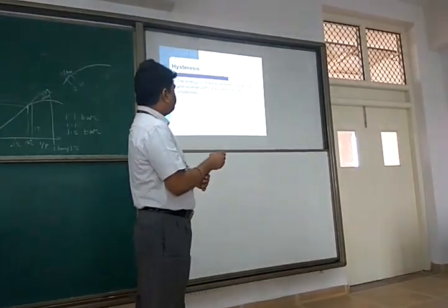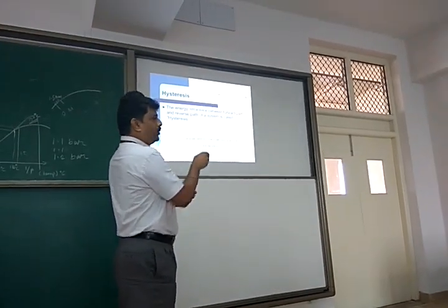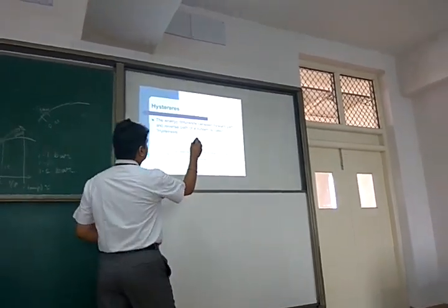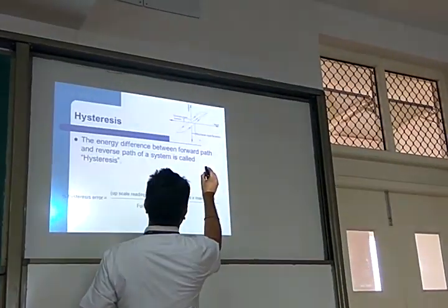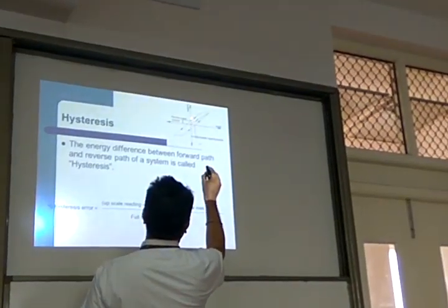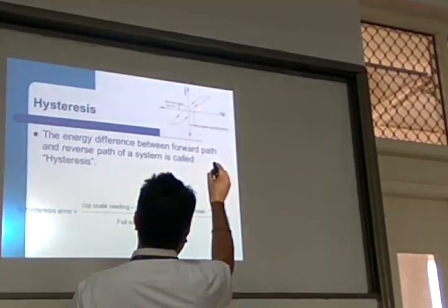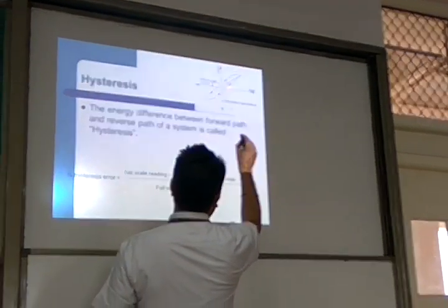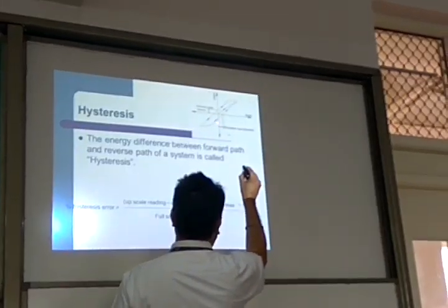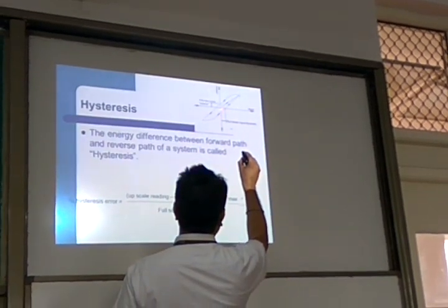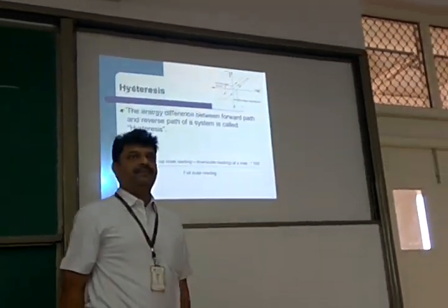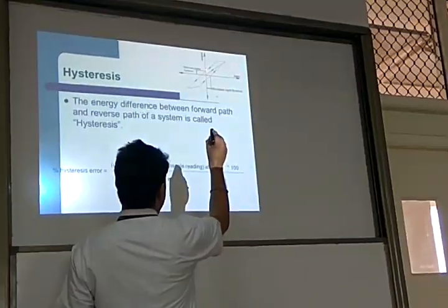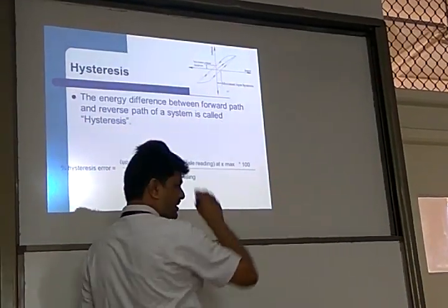Okay. So this is not only with respect to 0, also with respect to negative loading. It's not at any given point of time, it is the maximum difference between these two paths, a forward path and a reverse path. It's not from 0 to there. If the cycle goes on the negative side also, then the difference between these two is called hysteresis. Earlier I discussed only the positive cycle and said from 0 to the top, this difference is hysteresis.